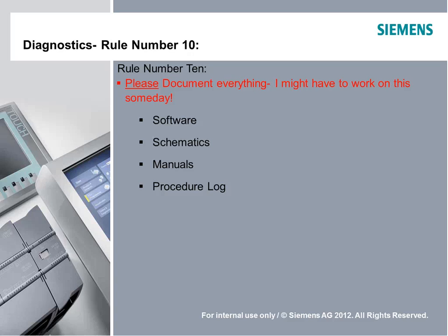A lot of the things that I showed today in diagnostic logs can be popped up onto an HMI screen locally, so you can have someone in the field able to see that diagnostic log and diagnose and fix intermittent problems or current problems as well. You can also pop up things like manuals and schematics in HMIs. If you design for maintainability, you're creating a machine that's going to have a lot better uptime. And if you're a machine OEM, then you're probably going to sell more machines.